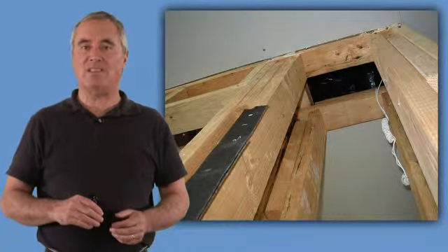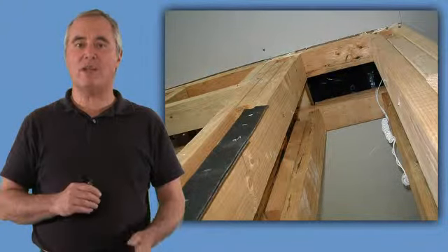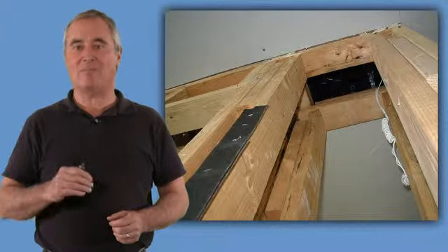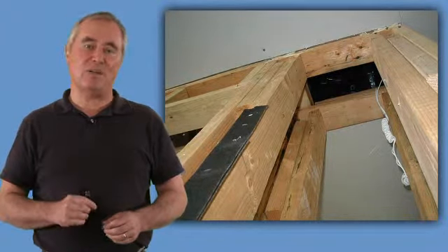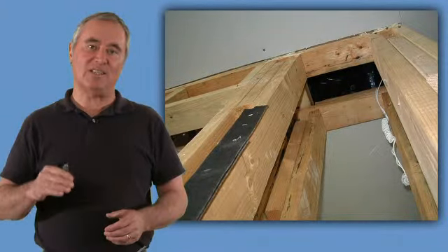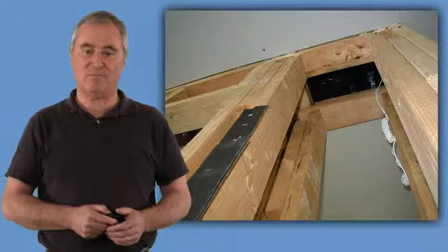We always want to seal holes that are located either high or low in the building, where the driving force pressures are higher, both high and low in the building. So big leaks, high and low leaks, and always leaks to the attic since our attics are so hot in many climates.